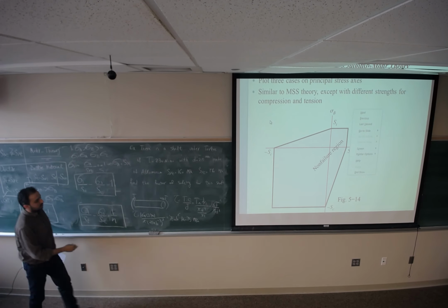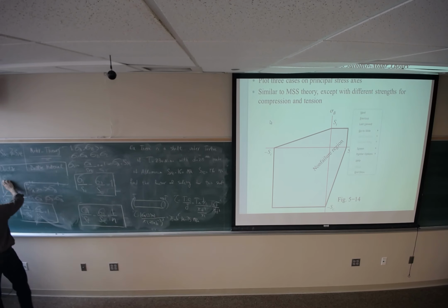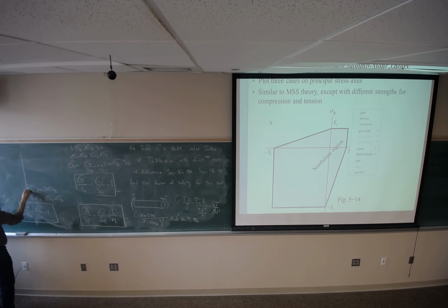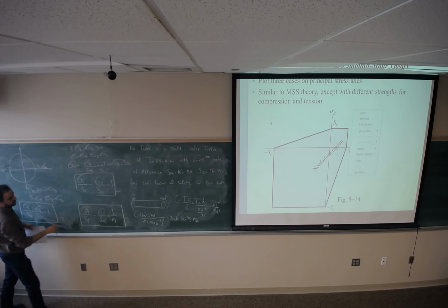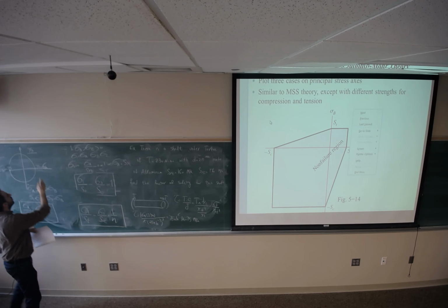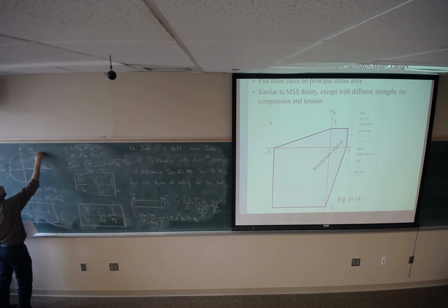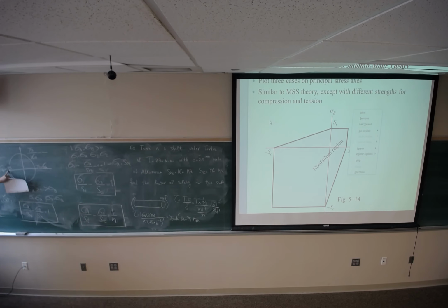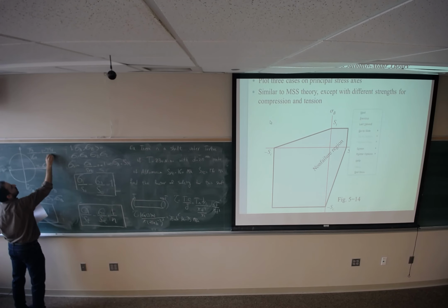So we have pure shear stress. For pure shear stress, if we draw the Mohr circle, it is going to look like this: 75, negative 75. This is sigma A, this is sigma B. So sigma 1 is 75, sigma 2 is 0, sigma 3 is negative 75. So just plug in here: 75 megapascal. SYT is in megapascal, so I don't change 75 to Pascal. Divided by 160, minus sigma 3, which is sigma B, negative 75, divided by 170, equals 1 over n.